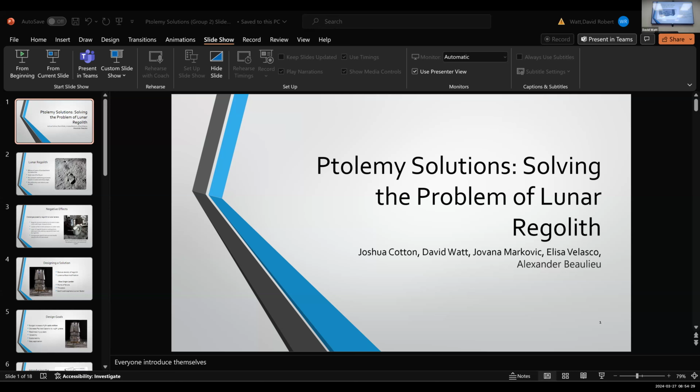We chose a pressurization of 2,000 pascals because the lunar surface itself has no atmosphere and has no pressure. So the pressure gradient was the most important part, with near 0 pascals. And we didn't need much energy because of the weight of the capsule, which we'll get into. So we chose 2,000 pascals, which will release just before the lunar surface, giving those quadrants enough velocity to spread out to their full width, and then land. And those quadrants will act as anchors to the lunar surface itself.